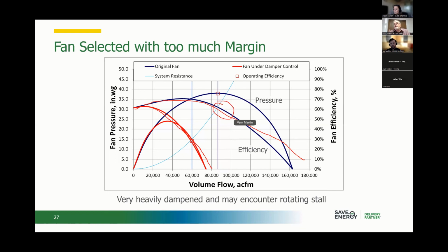And this is where you start getting into things like variable speed, and whether the variable speed can slow it down and satisfy both worlds. That's one of the big advantages of variable speed: you can be quite efficient at different points. The efficiency doesn't change no matter where you are along our system curve.